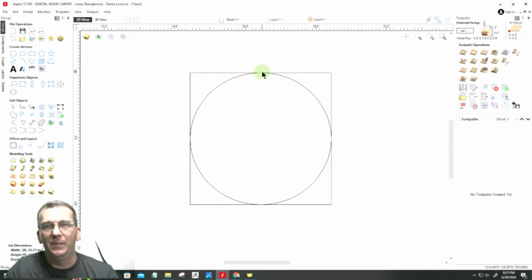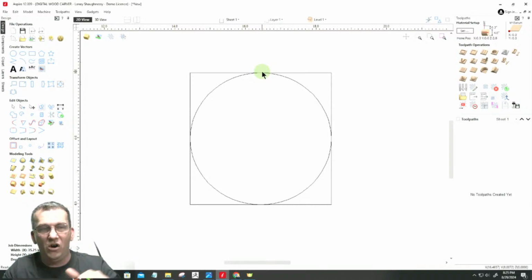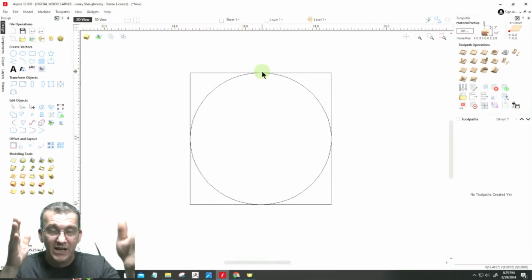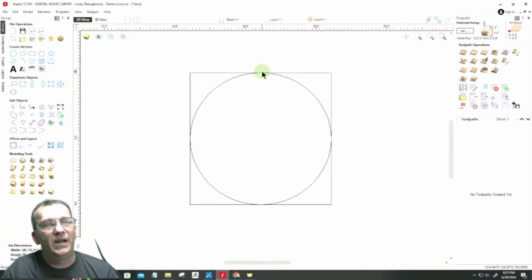Now I'm going to account for probably about a 1/16 of an inch. And so my finished out of a 4-inch blank, I'm going to probably end up about 3 15/16. That's a 32nd off the left and right side, or the top and the bottom.